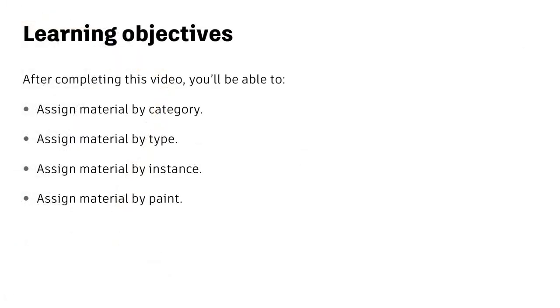In this video, we'll see how to apply materials to the category of an object. We'll see how to assign materials via type and instance parameters. And we'll show how to use the Split Face and Paint tool to apply materials to the face of an object.